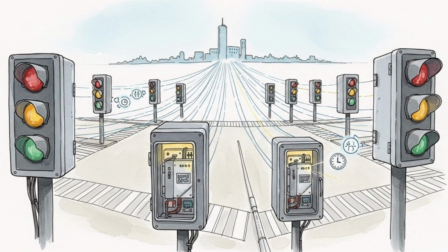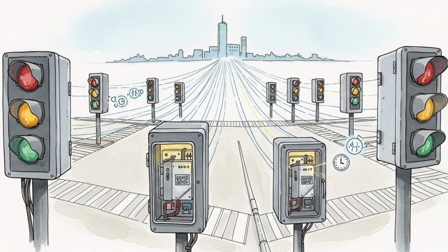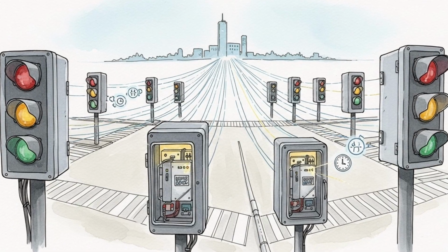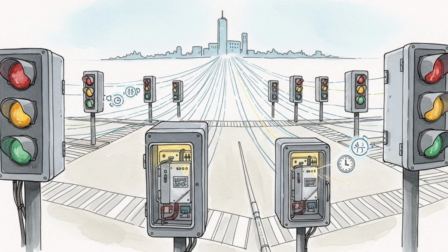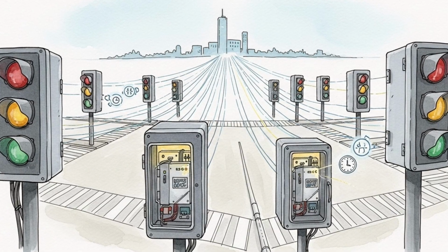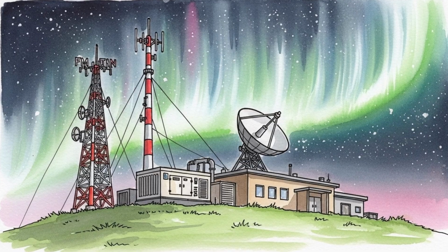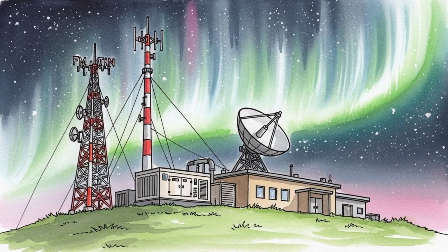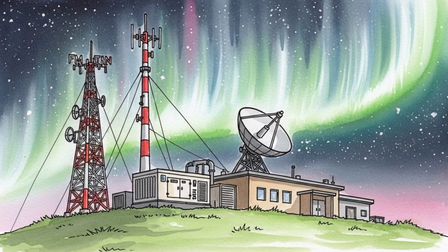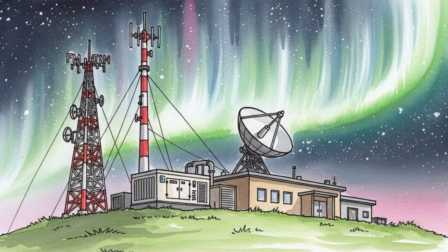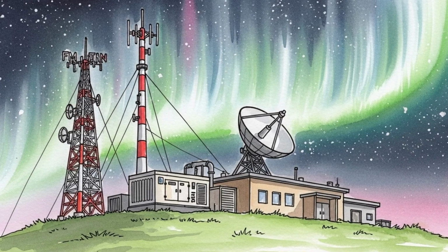Protection and controls must be considered. Differential relays use harmonic restraint to avoid tripping on inrush. During geomagnetically induced current conditions, even harmonic content can rise and confuse settings. Overcurrent relays may see distorted waveforms and respond slower or faster than expected. Tap changer controls can hunt when voltage sags slowly, which adds mechanical wear at a bad time.